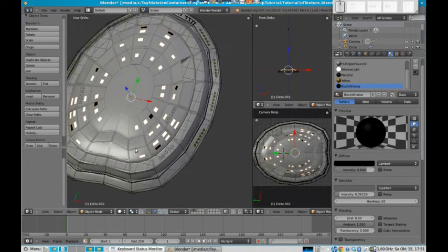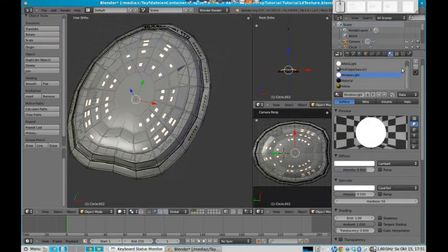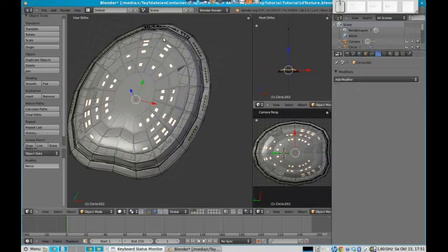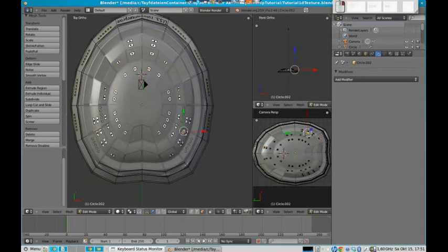Another thing here, considering just the windows, is that of course it should not be symmetrically on or off. So let's undo that and go to this modifier part, and since this is now another object, we can just apply the modifier and we will still have the modifier in our other two meshes. So the mirror modifier is just applied now to the windows. Now we have single control of each of them. Let's select randomly a few of them. This, maybe this one, and let's say